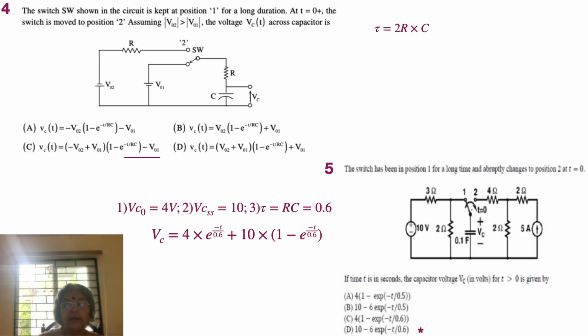Okay, you can even process it in a different manner, because if the capacitor opens out, then the current flows through the 2 ohms and cannot flow through the 4 ohm resistor because the capacitor is open. So it will flow through the 2 ohm resistor: 5 into 2, 10 volts. Okay, and the upper terminal is positive.